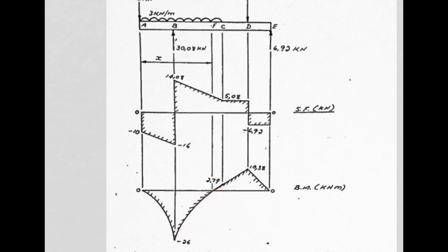And all we've got to decide at this point is whether they curve skyward or downward. Now remember what I said, if the UDL is above, they curve this way. So that means that that would bulge skyward, as I call it. So this shape is bulging towards the sky, as is this one bulging towards the sky, and it ends over there. So a curve, and that will suffice.